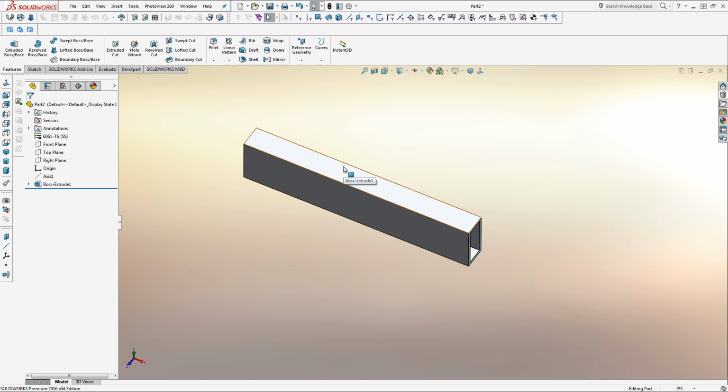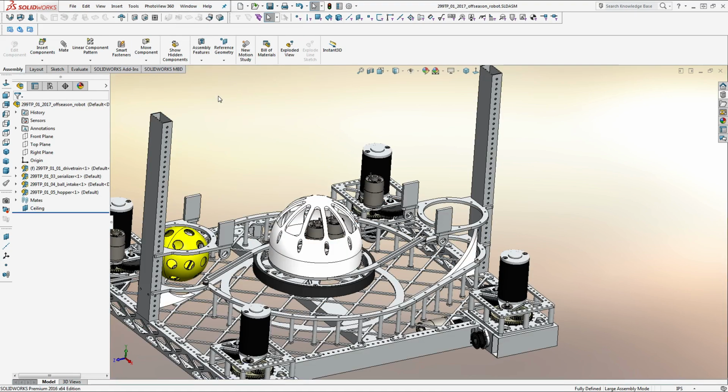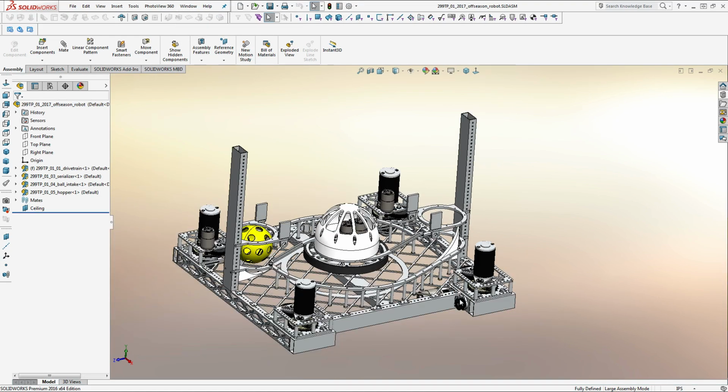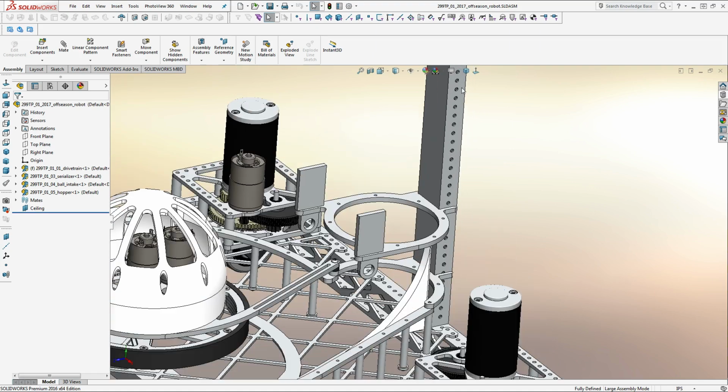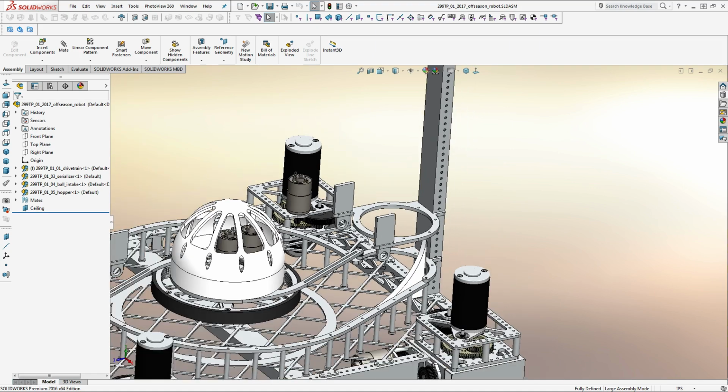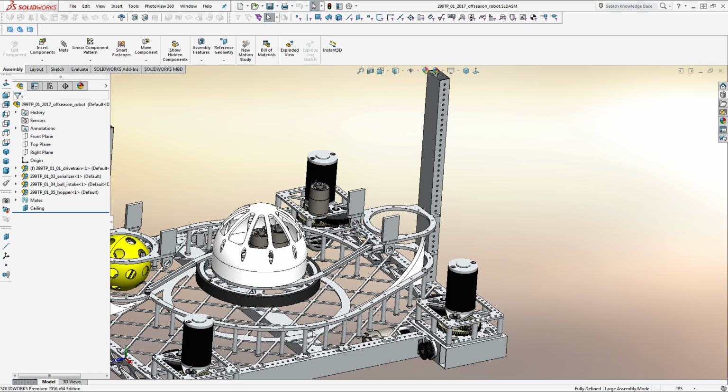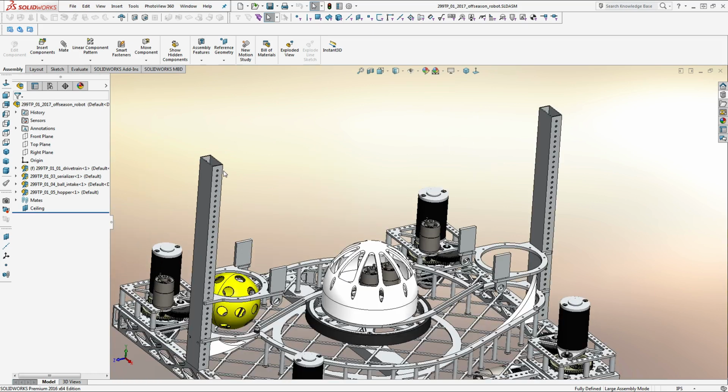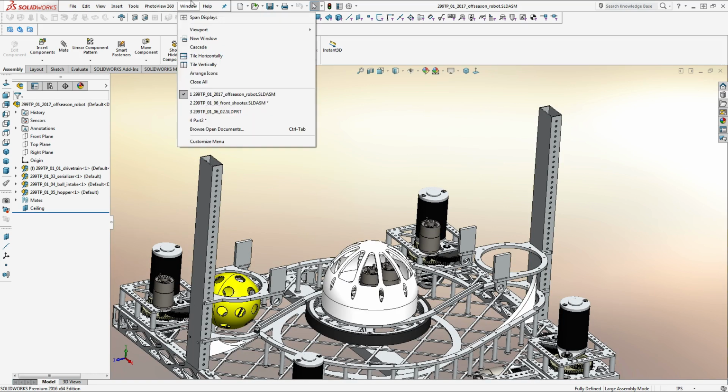So, depending on how you make your tubing, there could be an extra step. I usually encourage, for the most part, that you put a hole pattern in your tubing. What I mean by that is if you've maybe seen on, let me just drive the robot open. I do have the robot open. So like on the main robot assembly for the off-season project, you see you have a whole bunch of holes lined up somewhere, and most of them aren't used, but they're nice to have. They're 1/2 inch apart, and they're nice to have because mounting things gets so much easier when you have all these options that you can look to.